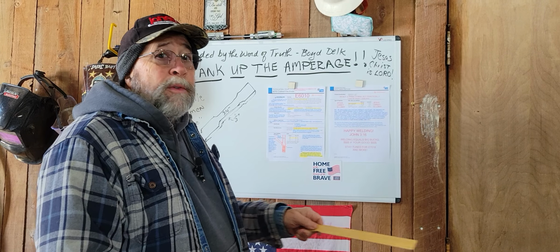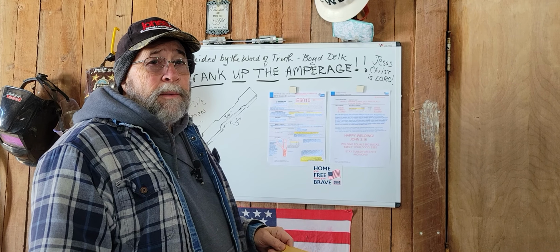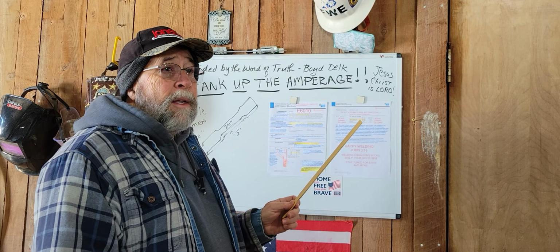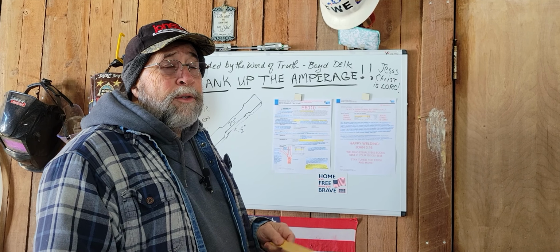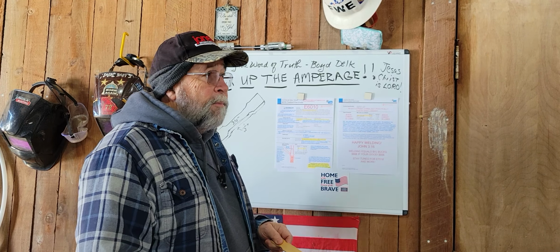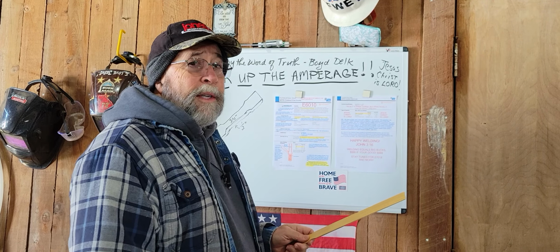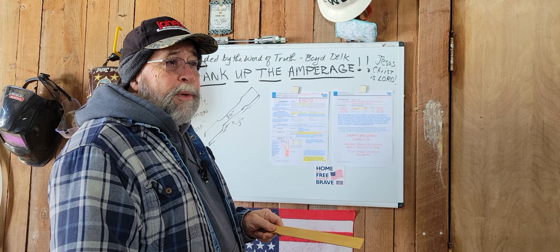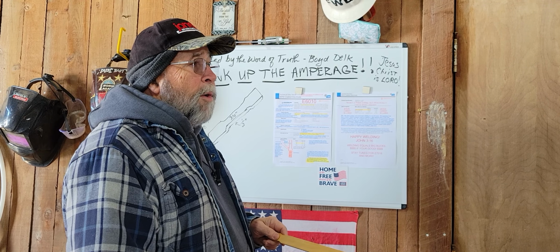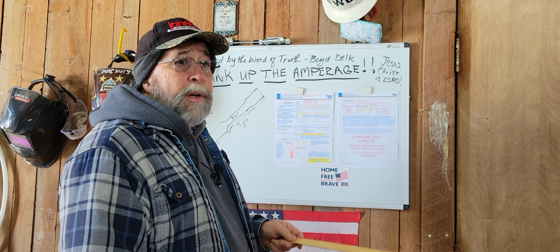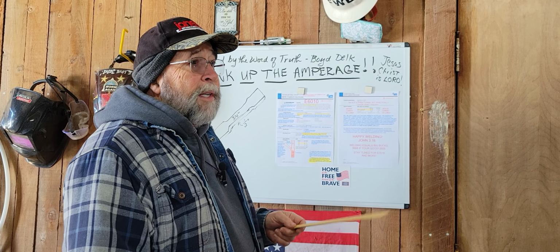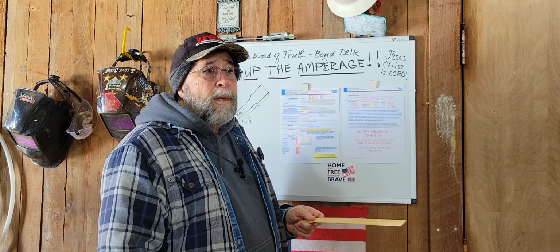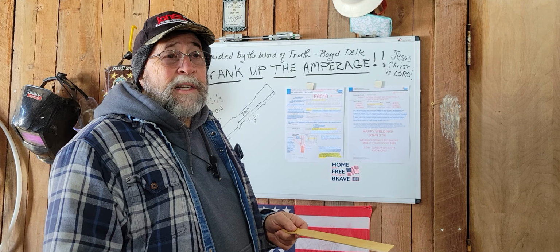So the most common, there are a lot of different techniques. Welders develop their own techniques, but I'm just going to share a couple of my own techniques with you this morning, hopefully to simplify and help you understand what motions or techniques you use with an E6010 welding rod. What is most commonly used is what's known as a whip and pause. That will work on flat metal if you're just putting a bead on flat plate. It will work on open butt joints, as in pipe, to give you a good root pass. So whip and pause is probably the most popular technique used in the welding industry, especially pipe.